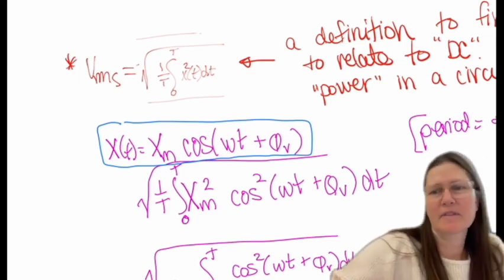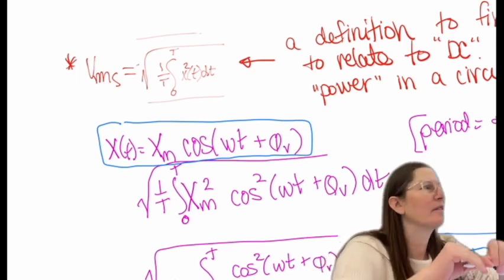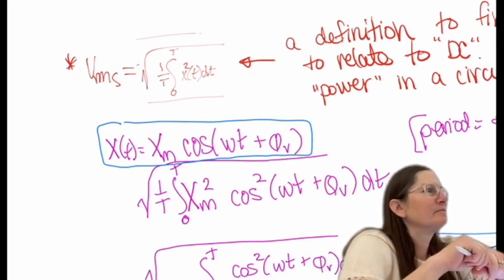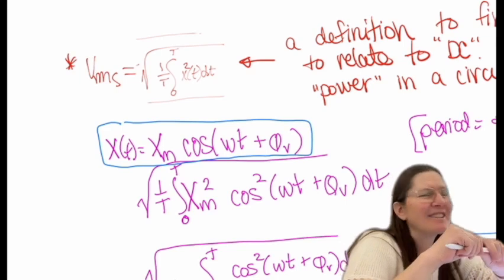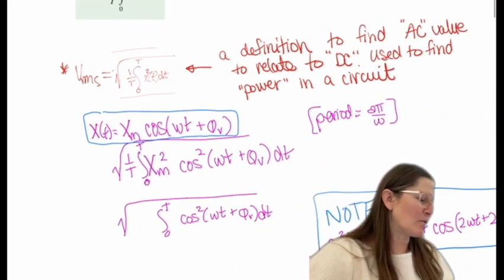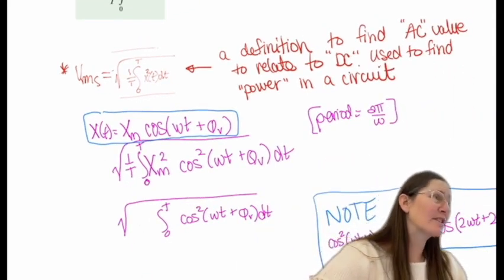Because let's say you have a sinusoidal wave, taking the regular arithmetic average, or what we normally think of as the mean, that would just get you zero. But we know we can still get power out of that. So taking the root mean square, or the RMS average, sort of lets you still get a term of power. It's how much current or voltage an equivalent DC source would need to have the same power output. Correct. Thank you.